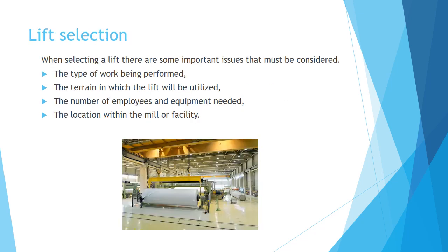Lift selection. When selecting a lift, there are some important issues that must be considered: the type of work being performed, the terrain in which the lift will be utilized, the number of employees and equipment needed, and the location within the mill or facility.